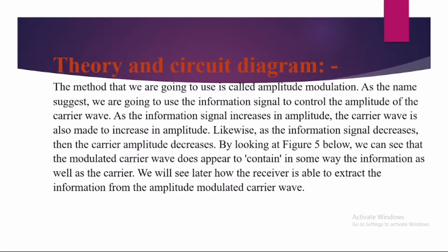In double sideband suppressed carrier transmission, the frequencies produced by amplitude modulation are symmetrical above and below the carrier frequency, and the carrier level is reduced to the lowest level. Actually, in AM modulation, DSB-SC modulation is used. In DSB-SC, both the sidebands are present while the carrier is suppressed at the output side.